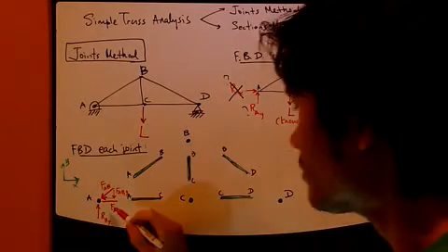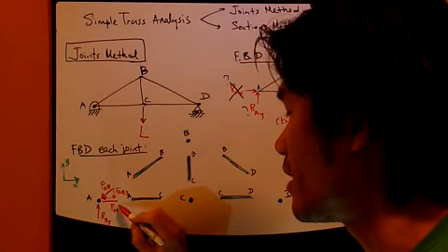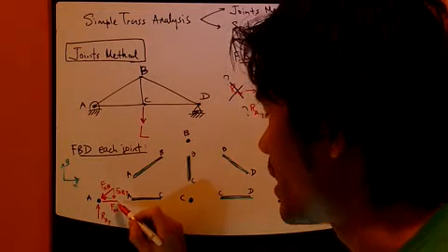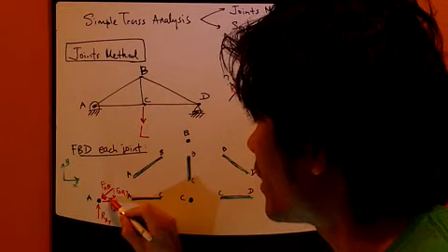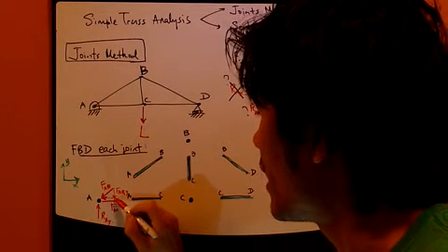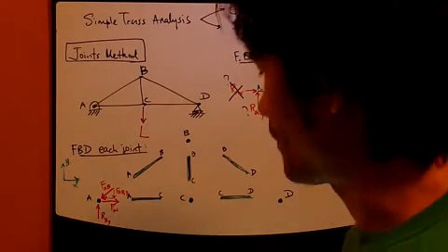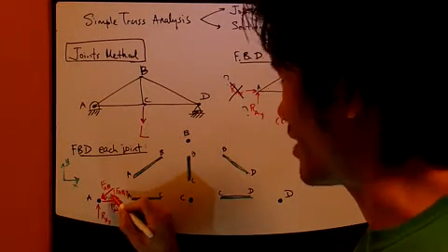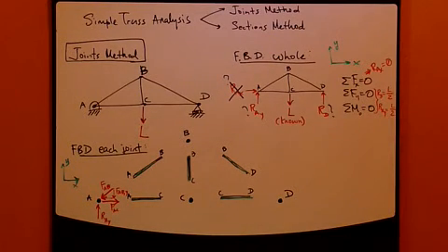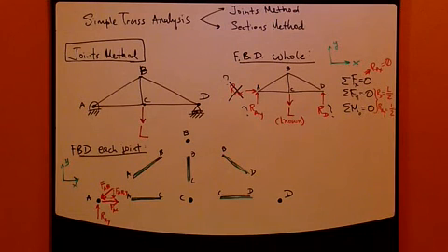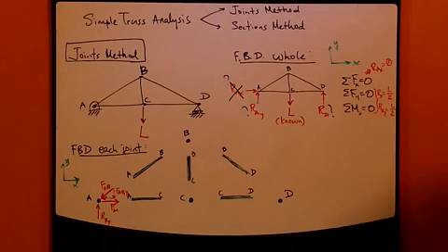Similarly, to figure out the direction of FAC, just look at the rest of it. Something must counter FAC horizontally. Look at this dashed line right here. This is the X component of FAB. It points to the left. Therefore, FAC must point to the right to counter this guy. This is actually FACX, but kind of cramped right there. So now the picture is complete, and I can actually draw this joint A separately. Okay, let's do that.